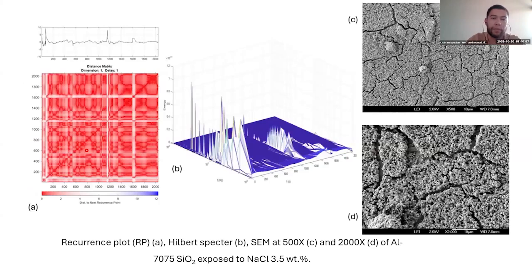On the other hand, when we have the sample coating, it is very interesting, because the micrography and the technique show how the localized corrosion is occurring, because we have attacks in this part, and in this part, that is in the cracking zones of the sample that I mentioned at the beginning of the presentation.